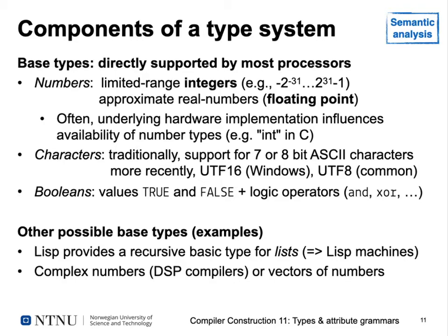So on a PDP-11, the machine Unix was first written on in C at least, an integer variable would be 16-bit. On an AVR microcontroller, which is an 8-bit microcontroller, you would expect an integer variable maybe to be 8-bit, because that's the largest amount of data the processor can handle with one instruction. But having 8-bit integers would break too much code, so the AVR GCC compiler writers actually decided, oh, let's use 16-bit integers for AVR code, which is weird.